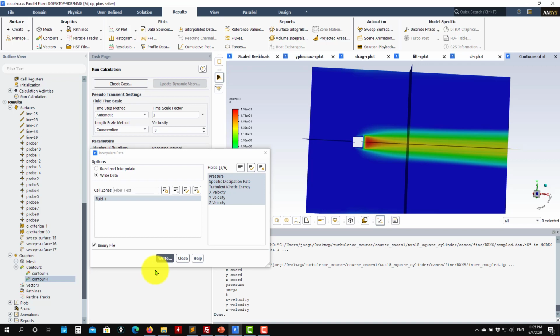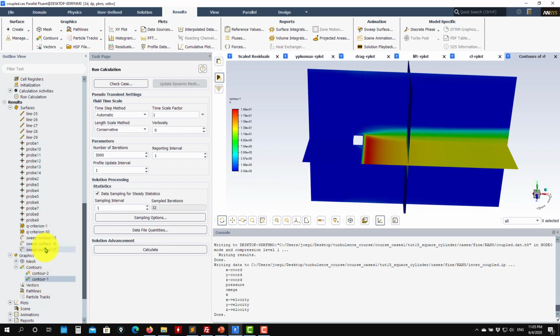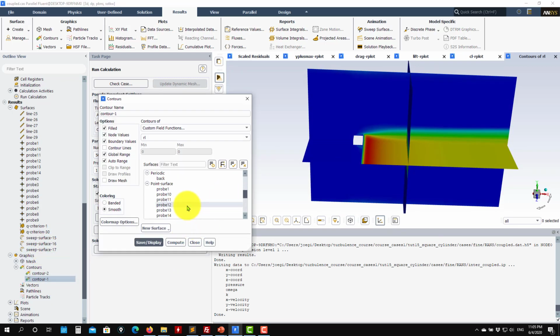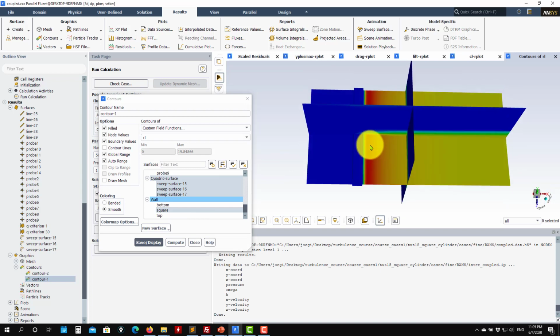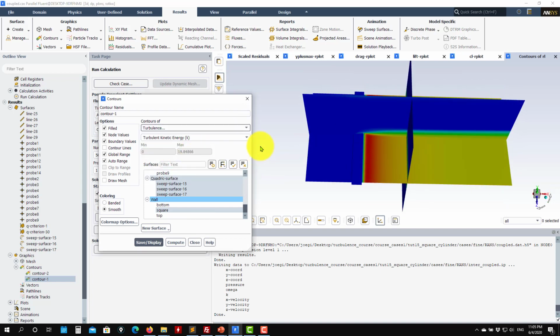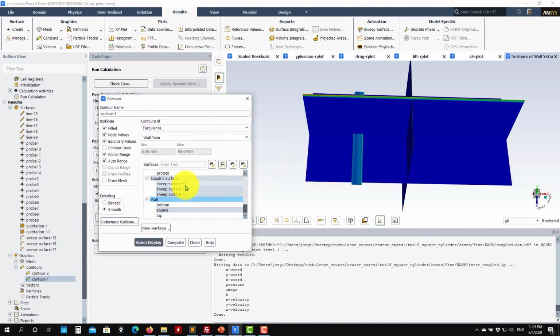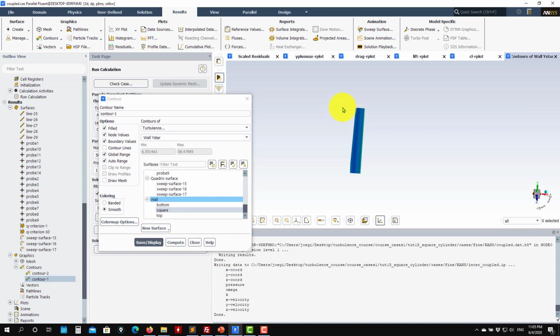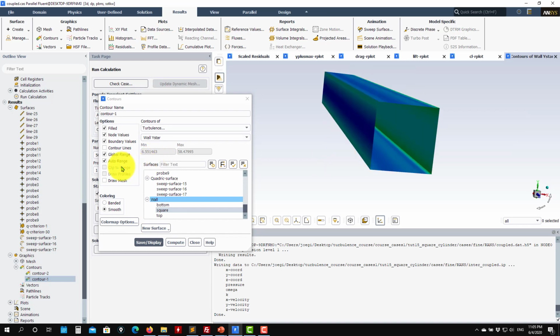And based on the length scales, then you have some other criteria for the mesh, but this mesh, you can see, is hexahedral. Also remember to plot your y plus on the surface. Okay, so in this case we are below 100, which is also recommended for SRS. So here, generally speaking, it's a very good value. Maybe we have a large percentage in the buffer area, the one that we try to avoid, but let's say that in this case it's not a problem. So see, it's well resolved on the surface.